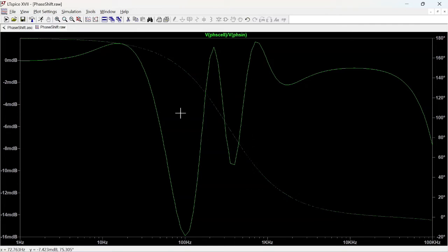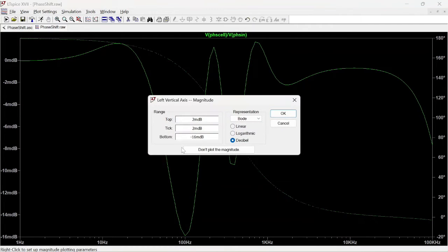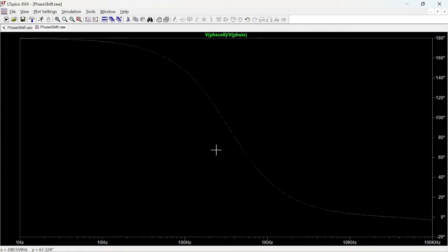And ignore this, we are talking about milli, this is just Spice doing its thing. This is 0 dB, so this is no amplification or attenuation of our signal, so it's really 0. If I get a better resolution, it might show a bit different. So I'm just going to remove magnitude. We don't care about that for now. We just want to see our phase shift.